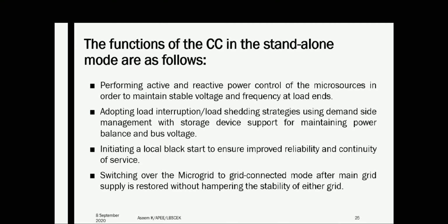The central controller decides such strategies as part of demand side management with the help of storage devices in order to maintain the power balance and bus voltages. It also initiates the local black start to ensure improved reliability and continuity of the services.